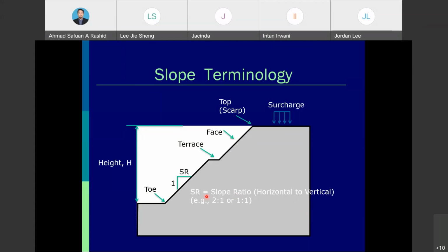For the soil slope, it is suggested to use 2:1. Is that referring to horizontal to vertical? It is not very common to use 1:1. Because, as a rule of thumb, if the internal friction angle phi is greater than the angle of the slope, we can consider the slope to be in a stable condition.